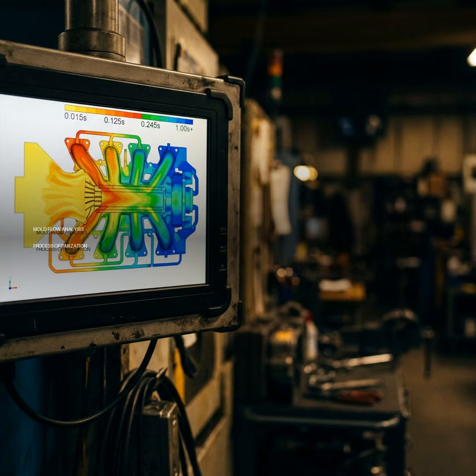And deflection? That's about warpage, right? Precisely, deflection is the total deformation of the part. It's influenced by cooling factors. Rapid cooling can lead to uneven shrinkage and the inherent shrinkage of the material itself. Molecular orientation can also cause deflection if polymer chains align in a specific direction. The report will break down deflection into X, Y, and Z components, so you know exactly how the part is deforming.